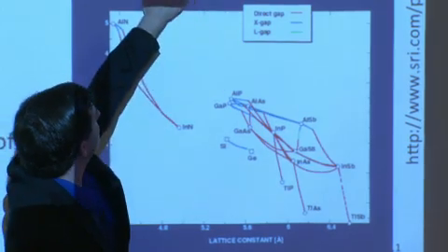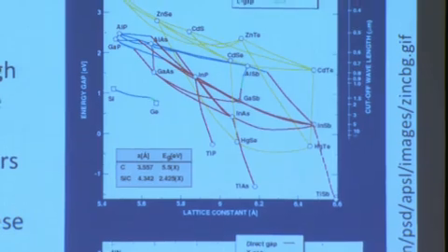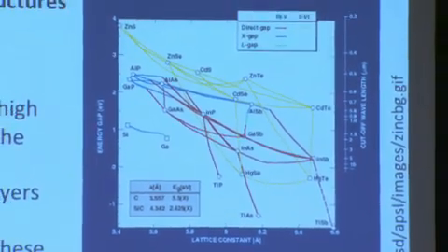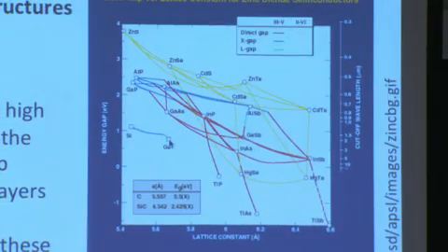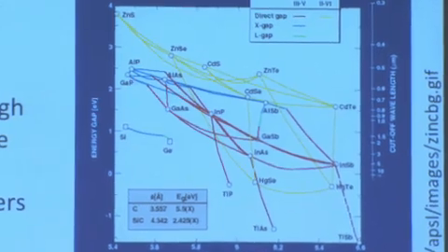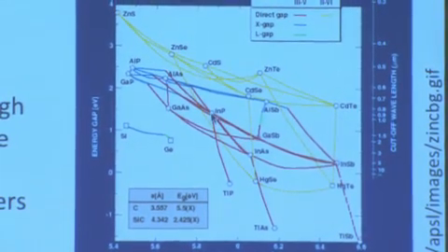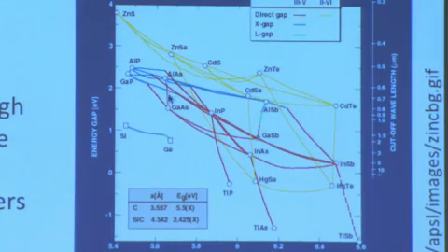So let's look at this growth system up here, the one that is typically used in high-efficiency solar cell materials. We have germanium right here, gallium arsenide, and indium gallium phosphide, which is essentially a mixture between gallium phosphide up here and indium phosphide down here. You can alloy the two together and get an indium gallium phosphide mixture and stack these 3 materials on top of one another, germanium, gallium arsenide, and indium gallium phosphide.